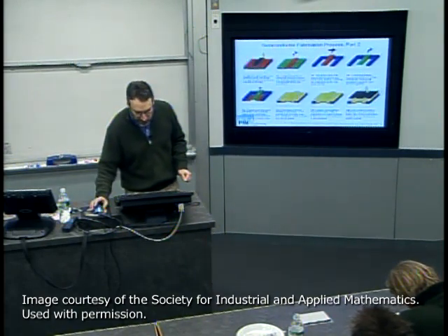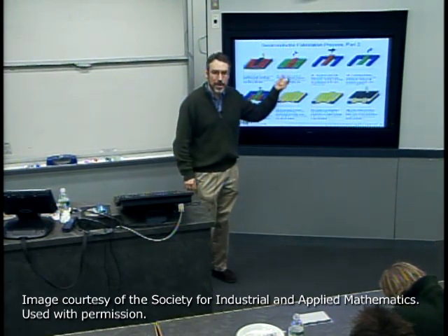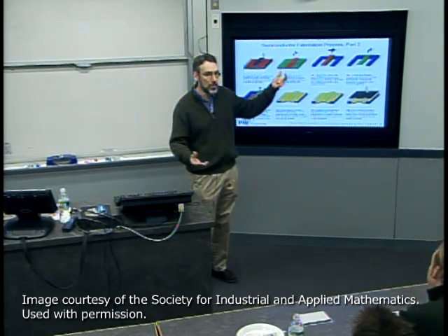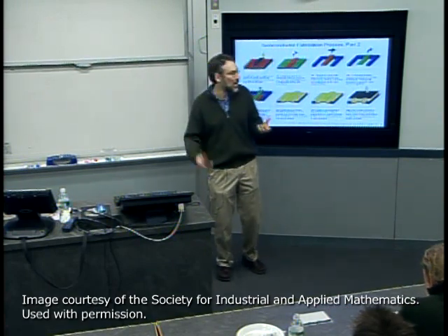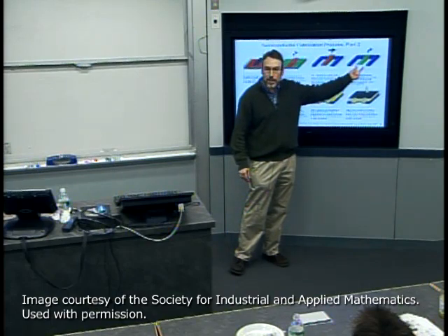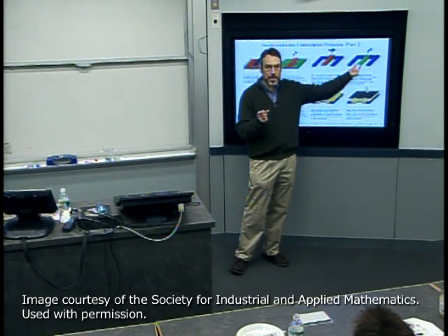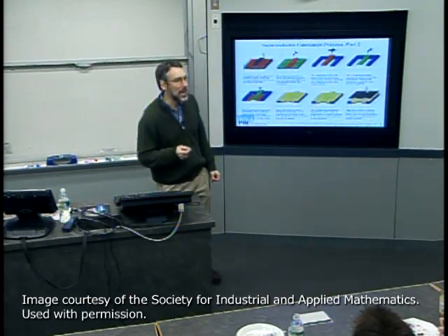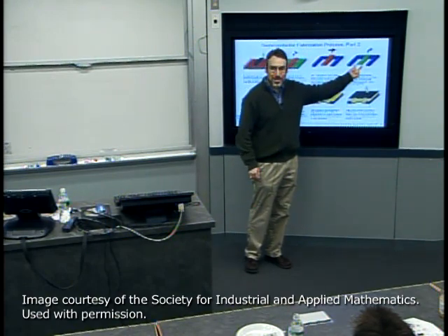In modern technology, in fact, that is perhaps the smallest lateral dimension that is determinative of the generation of the technology and the performance and characteristics of the technology. So if we talk about a 65 nanometer technology, they're talking typically about that channel length, that minimum feature size, being 65 nanometers.